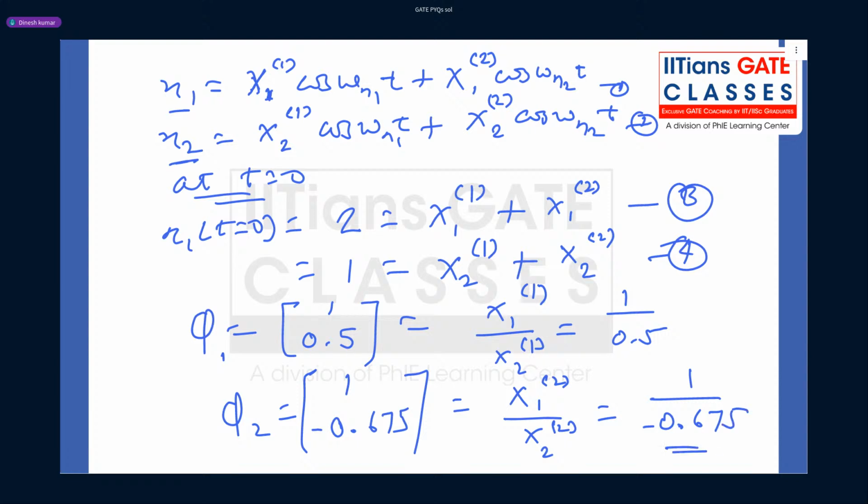Now guys, there is no role of all this data, because already we know in case of free vibration, the maximum amplitude of any degree of freedom is the initial displacement associated with that degree of freedom. Now all these are useful when there are other questions in GATE exam related to 2 degrees of freedom. You can see in GATE 2022, it's one of the very good questions they asked where all these details are useful. So those who are watching my session first time, they should know what all these details are.